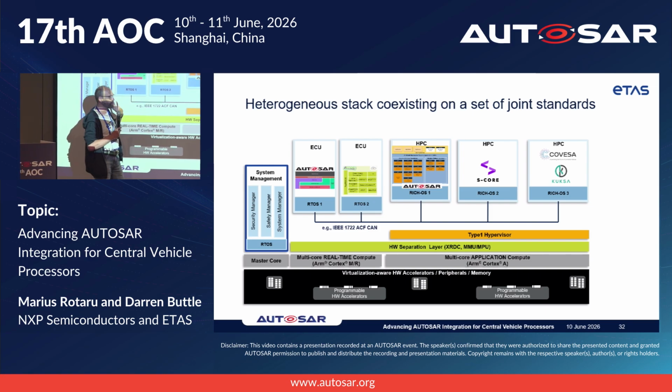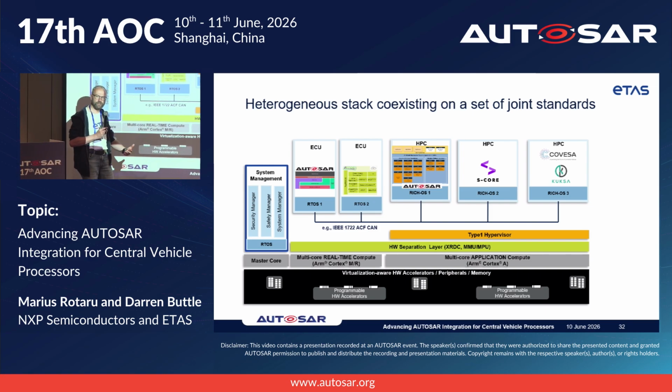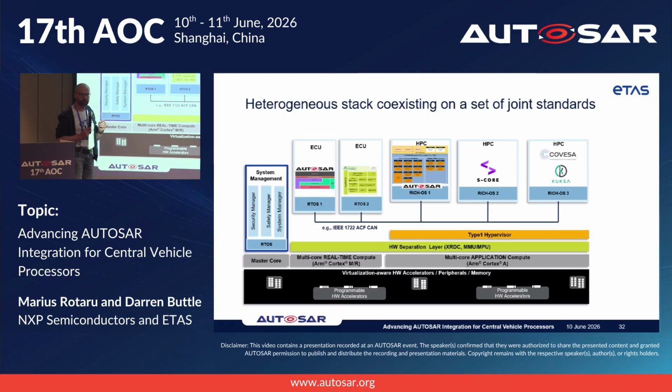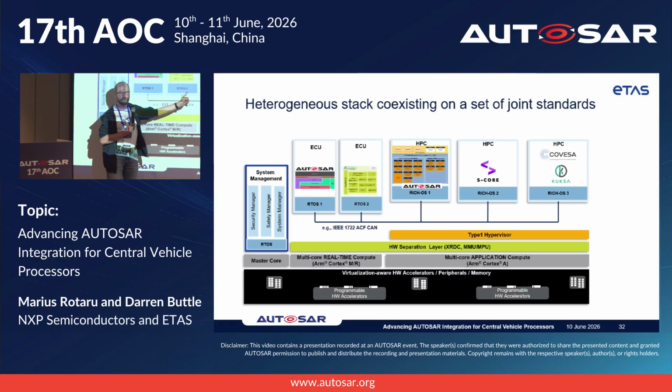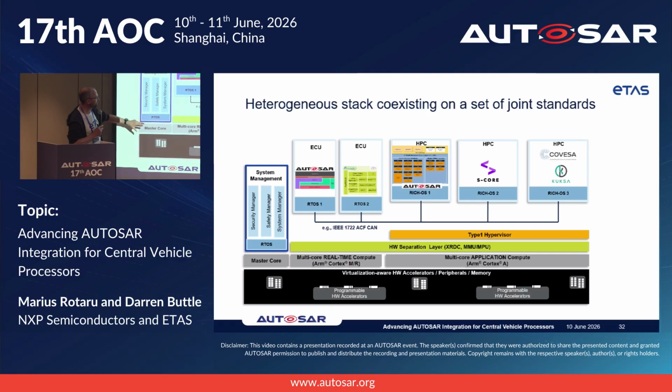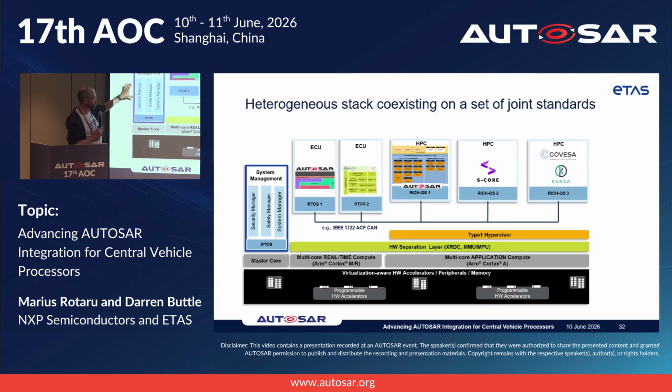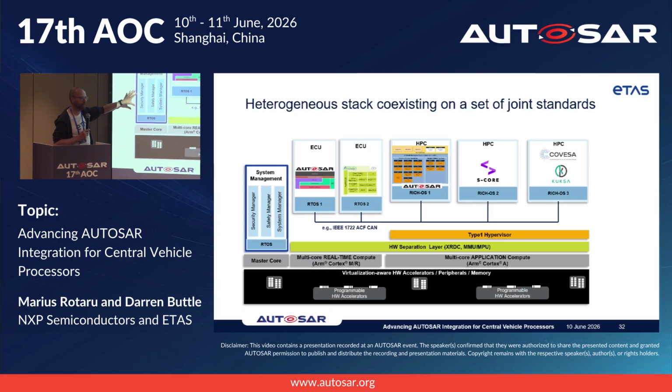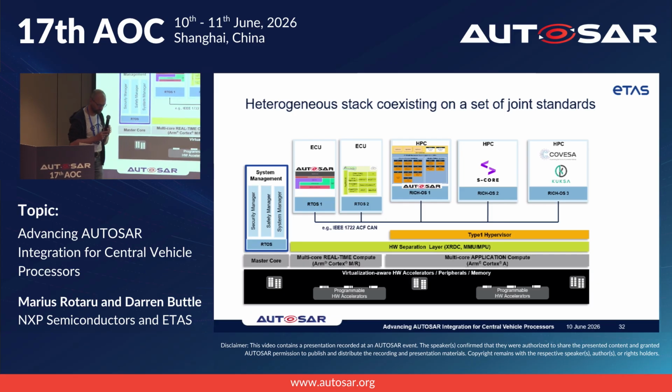But the overall things to do with the power management of the ECU and the boot up and the wake up of the ECU itself and management of the ECU hardware, somebody's got to take responsibility for this, and it can't be distributed across these other partitions, so it has to sit in here. So you actually tend to find that when people are deploying this, a lot of work goes into engineering the software applications that are running in the foundation subsystem for the purposes of managing the ECU itself.